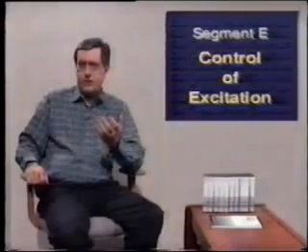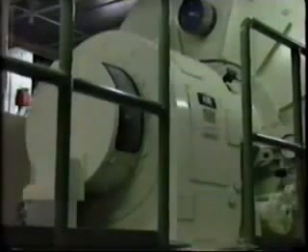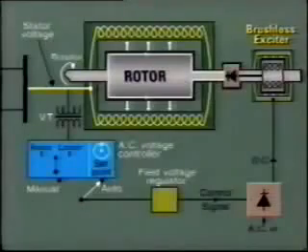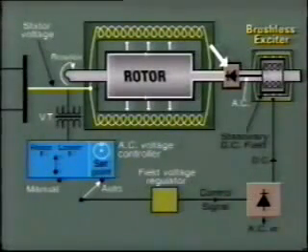Another type of excitation system often used with gas turbines is known as the brushless exciter. The exciter is actually a small AC generator which is built onto the end of the generator shaft instead of collector rings. In this exciter, a stationary magnetic field is provided from the DC winding, which is wound on the stator. The rotor winding produces AC voltage, and this is fed directly into diode-type rectifiers, which are built into the shaft. So we have, in effect, a rotating rectifier.